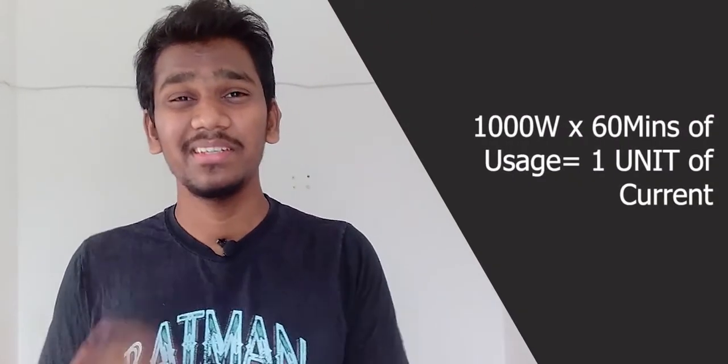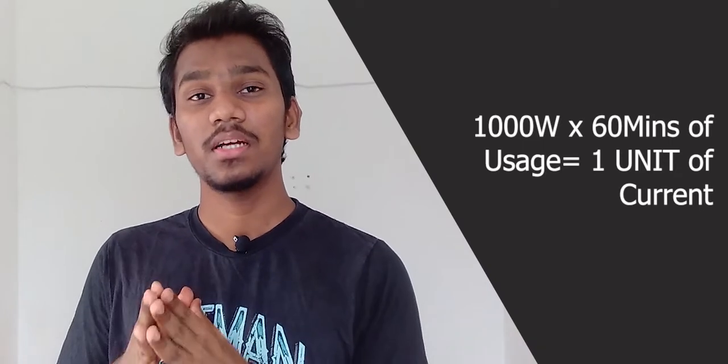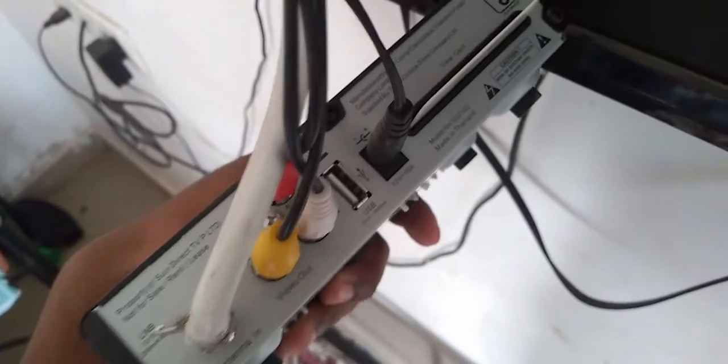Every month we pay the electricity bill based on the usage of units. The key point here is that if you use 1000 watts for an hour, that will consume 1 unit of power. For example, if you use a water heater 1 hour per day, by month end it will cost around 30 units of current. With this simple calculation, you can estimate your electricity bill for next month. Hereafter, before using any electrical equipment, just check how many watts it requires to run and see all the details.